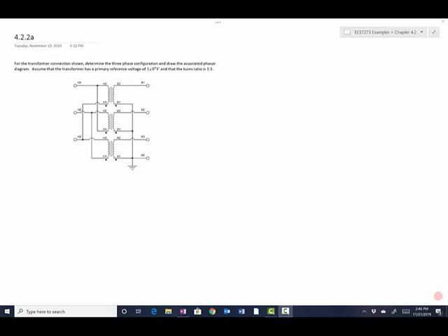thought of as three individual transformers wired together either in a delta or a Y, and there should also be some recognition that the way that they are wired together, in either a delta or Y, will influence the output voltage of the system. And we want to be able to understand and calculate what that relationship is going to be. Are the output voltages directly related to one another via the turns ratio, or are there other intermediary calculations that need to be done, such as converting between line to line and line to neutral, and then is there any lag or lead in the system?